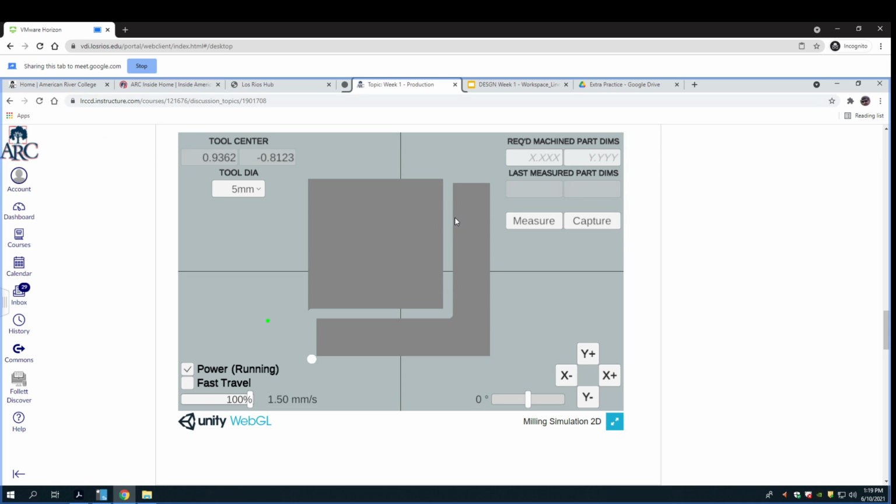That's called a fatigue loading. And if you do it often enough, it could break depending on what this radius is like, or it could not break. But that's a big part of the fatigue analysis when you do your strength. So these little radiuses in the corners are important.